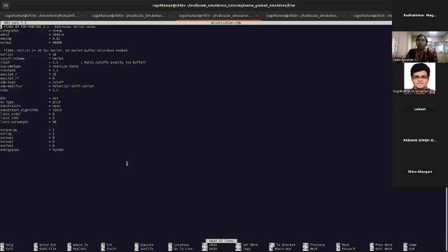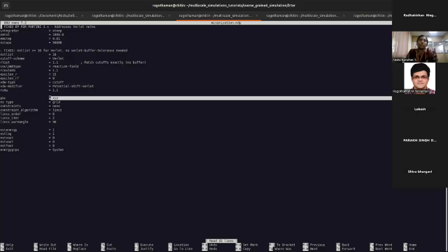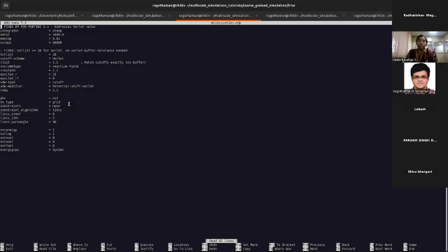So in order to ensure that there is no bias in the simulation, we are energy minimizing first. I've used 1000 steps here for the energy minimization. Mostly it will converge within these steps; otherwise you can increase the number of steps and see whether it converges or not. These are the other parameters, like the neighbor list, how many neighbors it should calculate, the cutoff schemes, the Coulomb type for the charge calculations, as well as the Van der Waals interactions, like non-bonded interactions. And PBC you can give as XYZ, if you're not sure what PBC you want, in all dimensions.